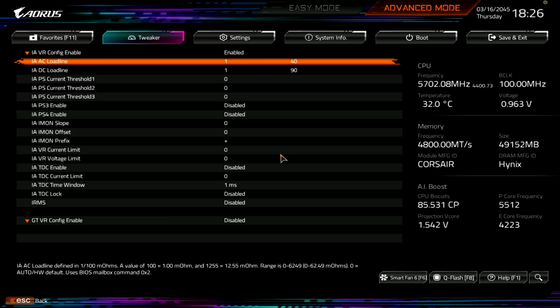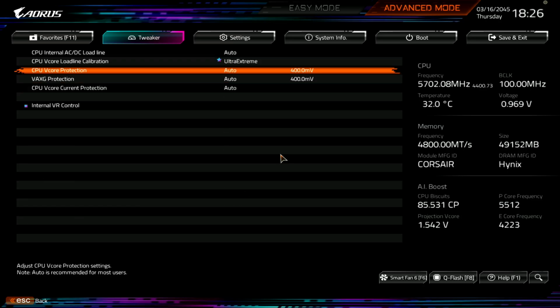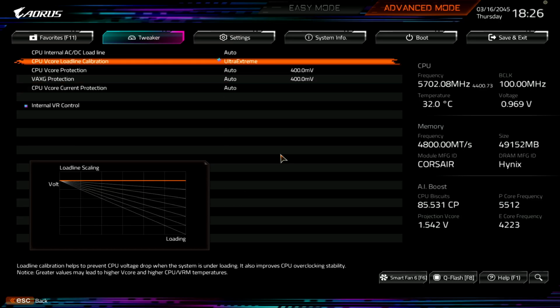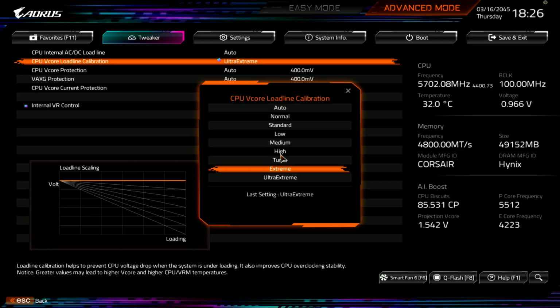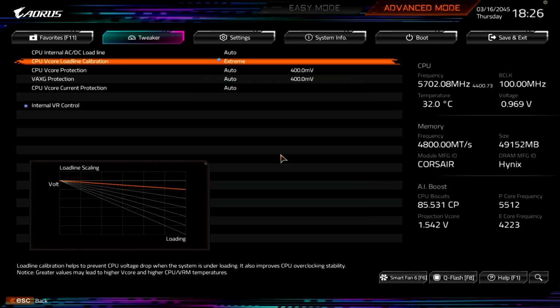Technically it is possible to tune voltage controllers to work with extremely flat load lines, but I don't know if every motherboard is configured for that correctly out of the box, and I have encountered motherboards that aren't. Admittedly, on AM5, not AM4 or LGA 1700, and using a Monolithic Power Systems controller, not a Renesas. But just in case, I would generally recommend that you don't take the chance that maybe the VRM isn't properly set up for zero V-droop operation.